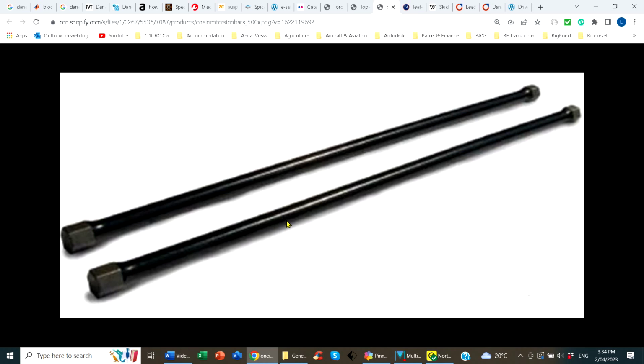They're often used in armoured fighting vehicles for that reason. It is also possible to nest them, to have a solid bar inside a hollow bar, and you get extra deflection because you've now got twice the length of bar working. That can also give you some level of progressive response, because as you move from one bar onto the other, you can change the rate.